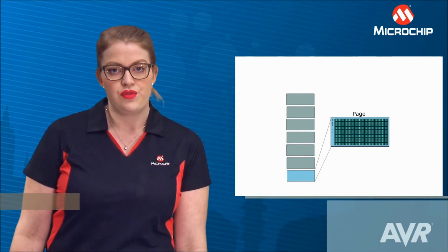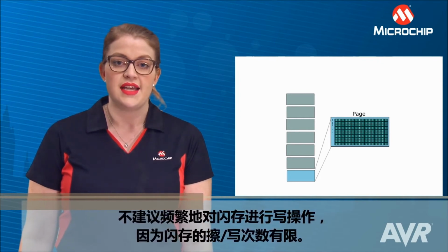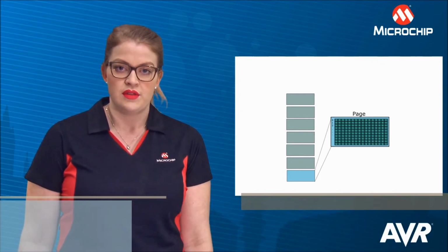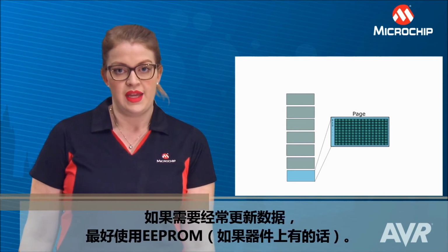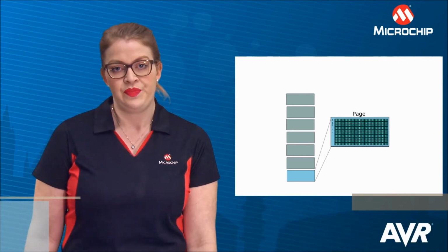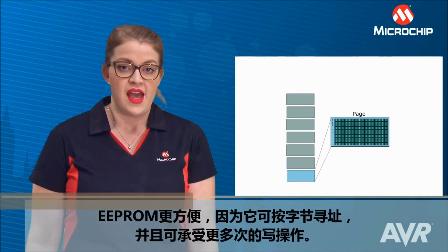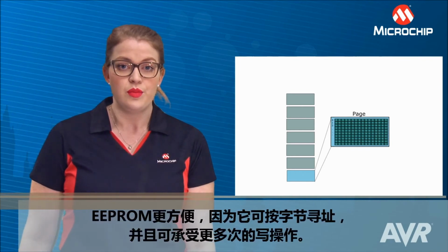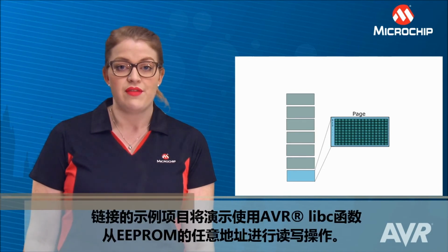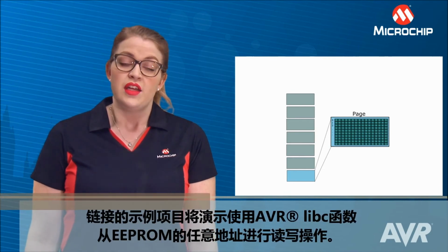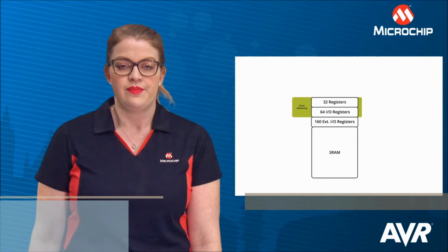It is not recommended to write to the flash too often, as it has a limited number of erase write cycles. If you have data that needs to be updated often, it's better to use the EEPROM if this is available on your device. The EEPROM is more convenient, as it's byte addressable, and will handle more write cycles. The linked example project demonstrates reading and writing from an arbitrary address in EEPROM using the AVR libc functions.